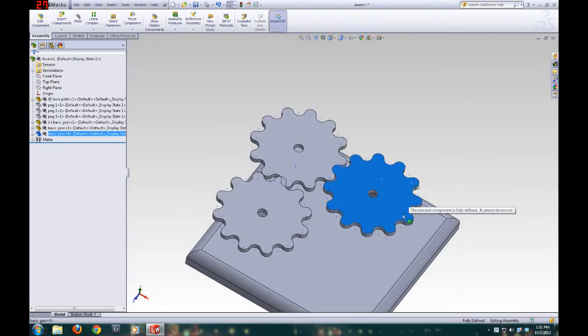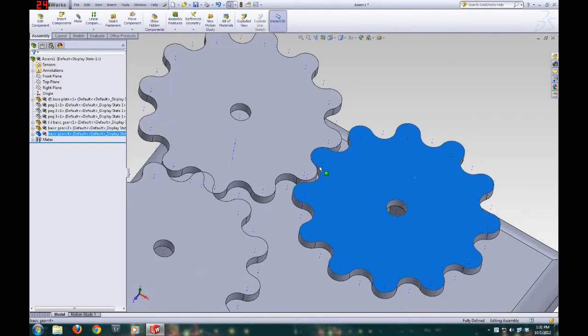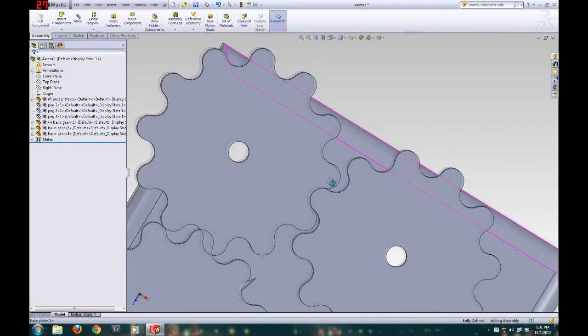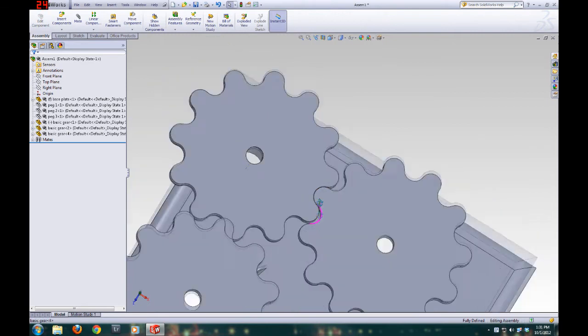We come back here and try to rotate the gears, and it won't, because we've stipulated that those axes are perfectly together. If this gear rotated at all, they'd be ripped apart. So you've put in this implicit anti-rotation constraint temporarily. That's the key. So now we know that these gears are meshing perfectly because those two axes are aligned.